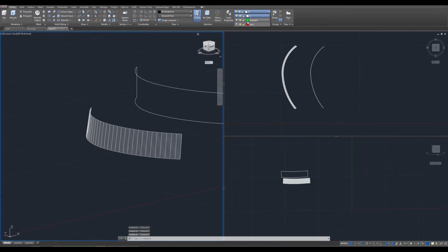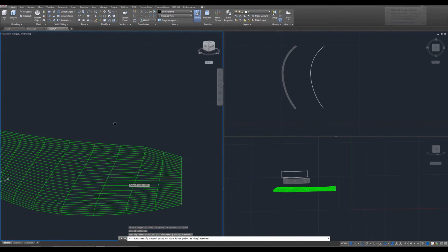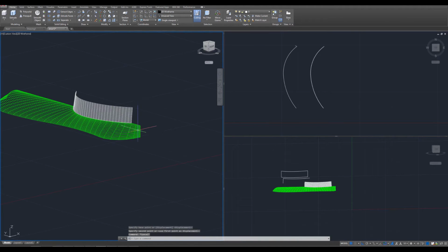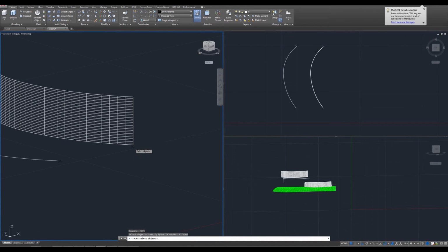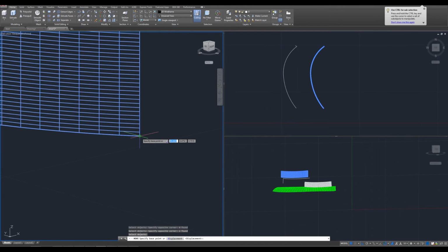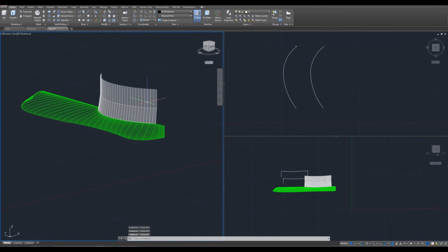I'm going to turn on the second part now, and I'm going to try to move this over, move, select that object, press enter, select a point, and then this should go at this point right here. Okay, and then I'm going to go back here and use the edge surf command to select these points. Okay, and then use the move tool. Whoops. Enter. And I'm going to select that point and combine it to that point up here. Okay, so that's looking good.